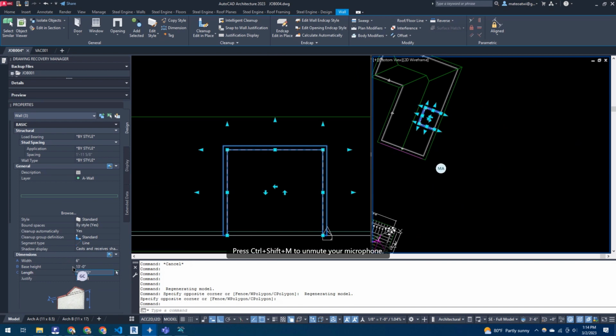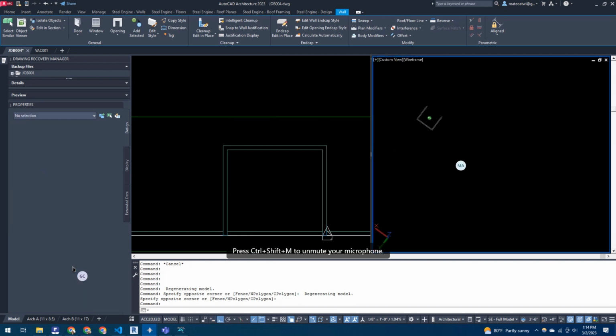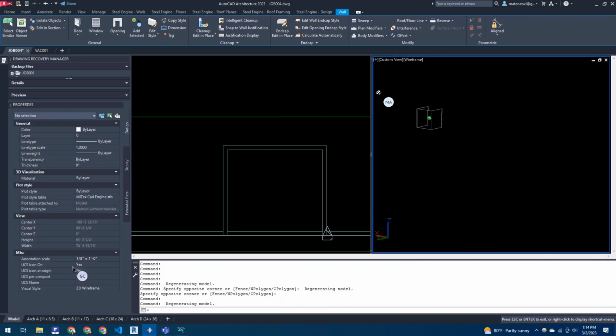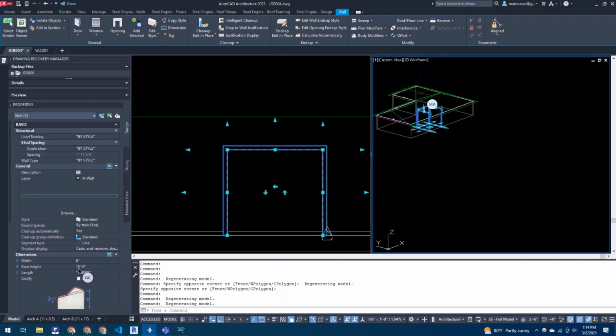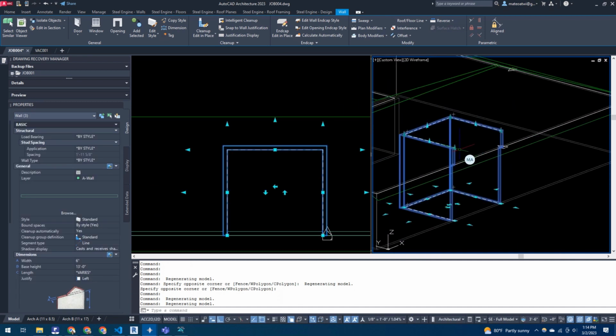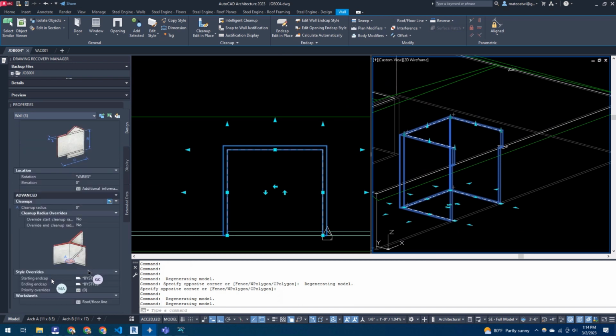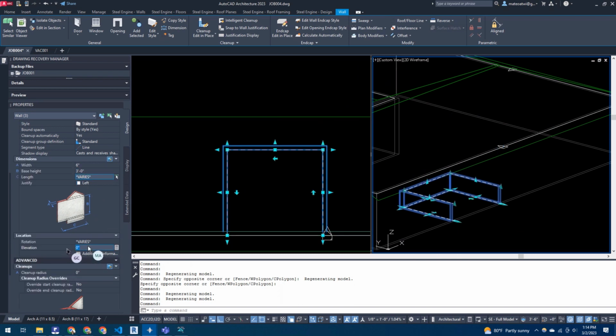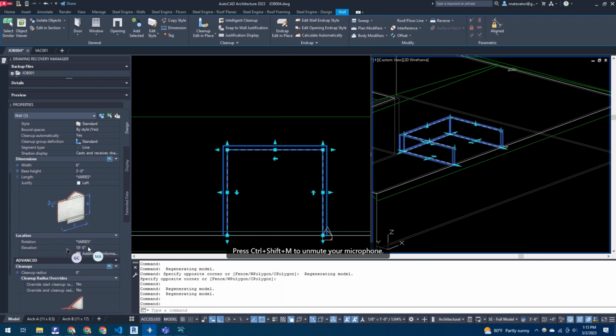Okay, and then scroll down. Hold up one second, I'm trying to get a view of this one over here. Actually, I should have had you do that a little bit different. So instead of base height being 13 feet, what you can do is say your base height like 6 feet or 5 feet, or make them 3 feet, just for the sake of argument. Then go down to elevation, change the elevation to 10 feet. So that pops it up there, and you don't have to have that giant wall there. And then you would put planes on that.